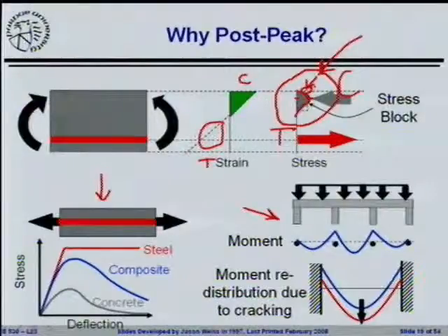Now, I mentioned last class sort of in a casual way, in the early 80s, all of these design equations changed. All of those equations came in where they started to say, well, what happens if you get higher strength concrete? Because the field went from 3,000 psi concrete to 8,000, 9,000 psi concrete. High strength concrete is born. The equations aren't predicting what we should be getting anymore. So they went in and altered some of those factors that take you from a stress-strain response to the rectangle, Whitney stress block type response. The alpha and the beta factor, those scaling factors come in there.